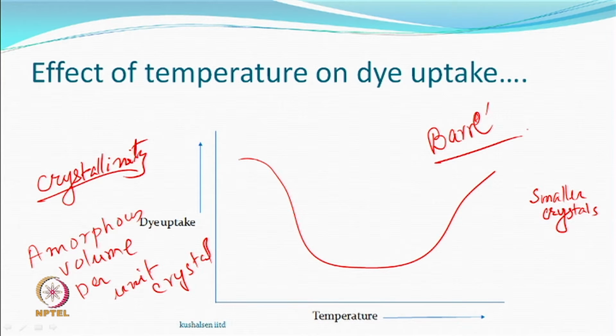So, as a customer you would like to reject this; it does not look good. You wanted uniform dyeing and the textured yarn is not uniformly dyed. And so, somebody who is optimizing the temperature, the first parameter you were looking at was the crimp rigidity, because you are preparing a textured yarn, and suddenly you find there may be something else you must look at, which is not tensile strength or abrasion resistance.